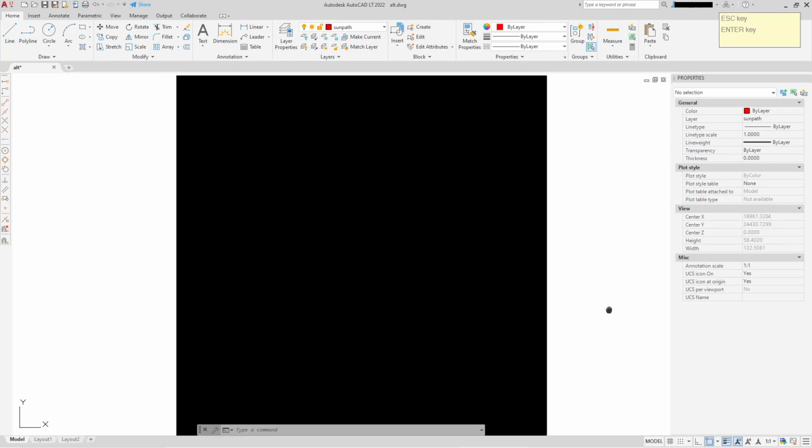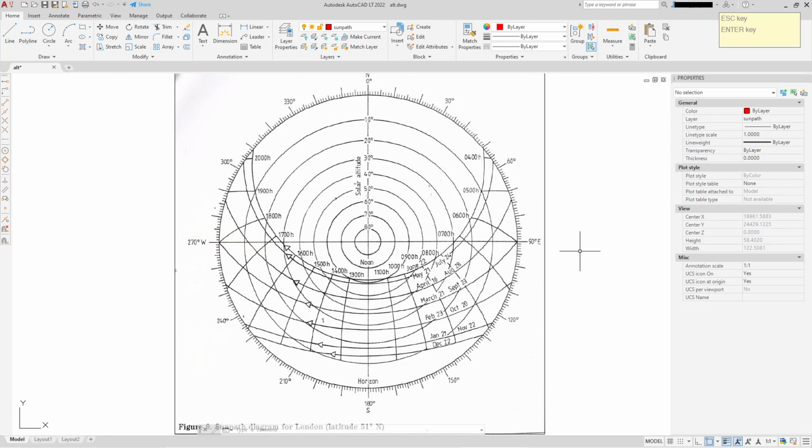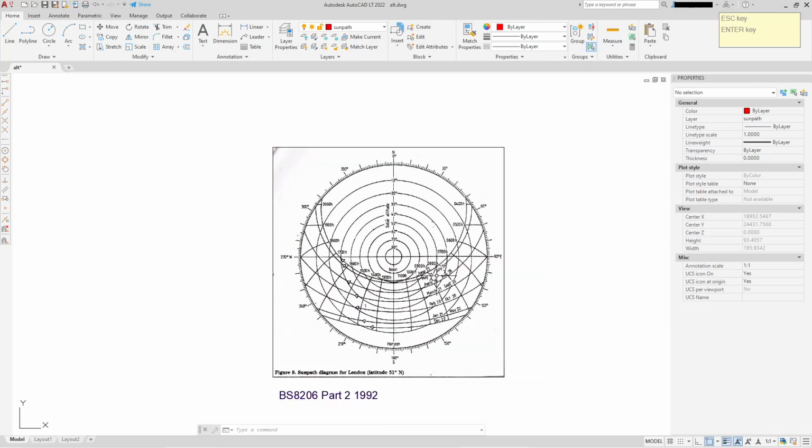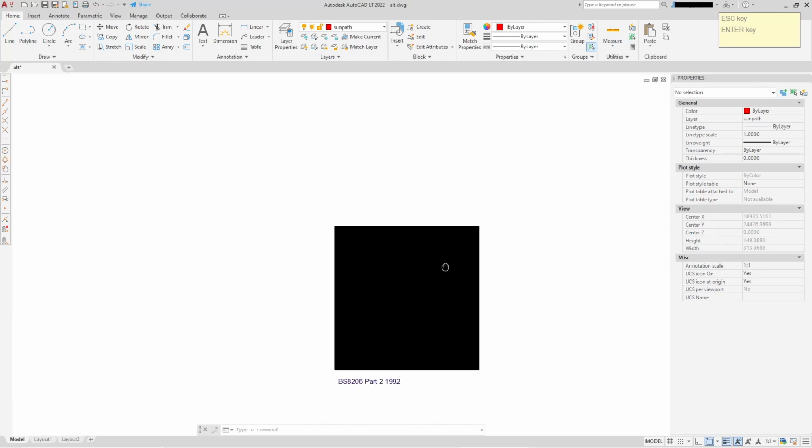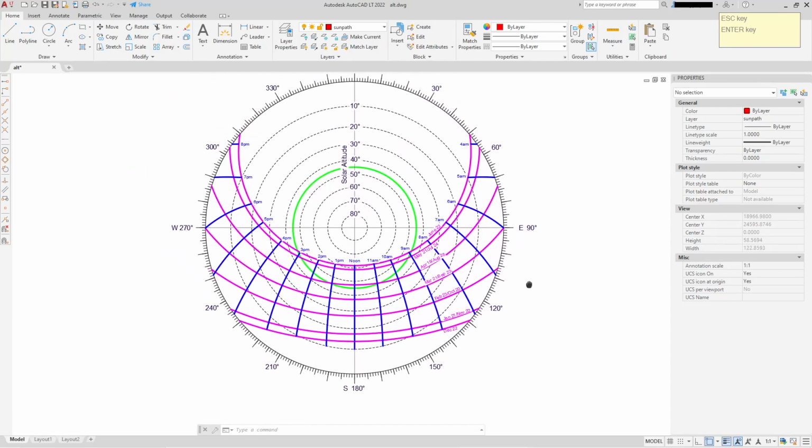But it's really a great little diagram, because he's mixed the sort of map position with all these angles around the outside with the solar altitude, and then he's plotted the sun paths for different times of the year with hours of the day, which means you can work out for a particular day of the year the sun's altitude and the time it'll reach that altitude, etc. It's really quite useful. I've redrawn it so it's a bit clearer.